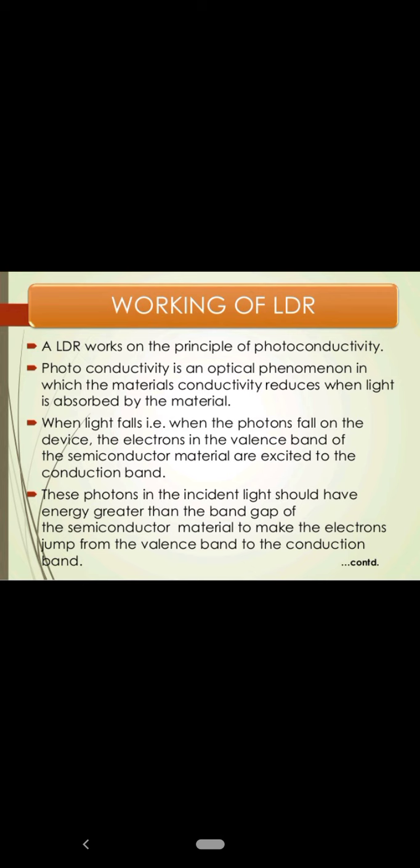So let's now understand the working of LDR. LDR works on the principle of photoconductivity. Photoconductivity is an optical phenomenon in which the material's conductivity increases when light is absorbed by the material. When light falls, that is, when the photons fall on the device, the electrons in the valence band of the semiconductor material are excited to the conduction band. The photons in the incident light should have energy greater than the band gap of the semiconductor material to make the electrons jump from the valence band to the conduction band.